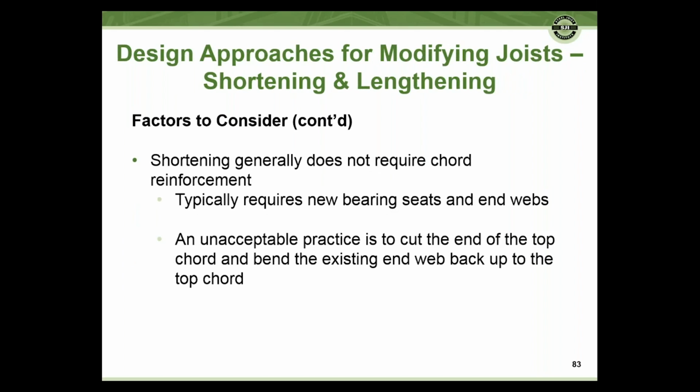Again, more factors to consider when you're looking at shortening a joist. Generally, when you're shortening a joist, you're not going to have to reinforce the top or bottom chords. You're going to need new bearing seats, obviously, and you're going to need new end webs. Make sure you get to design those. Again, when you do cut it, you're possibly going to remove some of that camber.